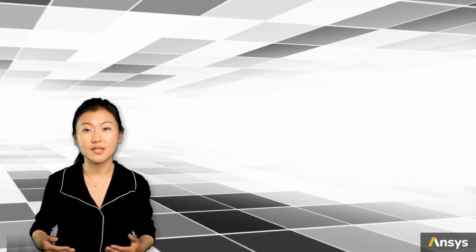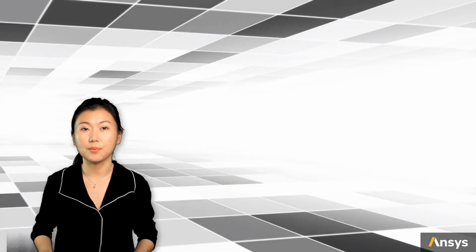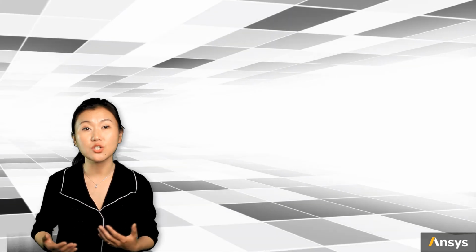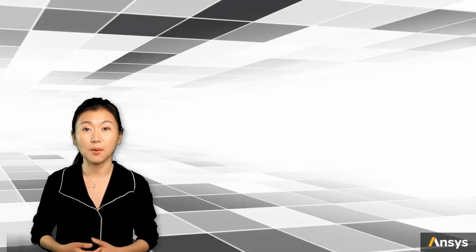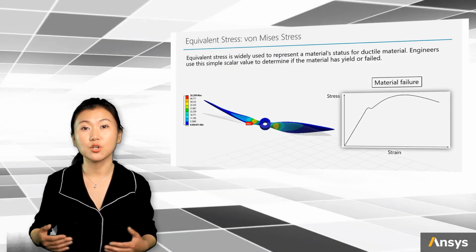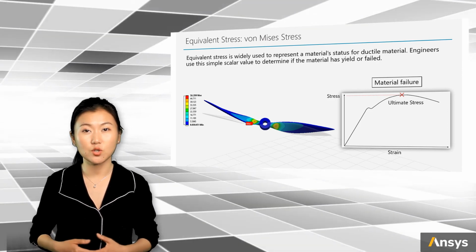In summary, we can see that only when the differences between the three principal stresses change, the von Mises stress will be affected. And that's why von Mises is a good equivalent stress to represent the distortion of a material instead of the absolute value of each stress component. Engineers use this simple scalar value to compare with material strength and determine if the material has yielded or failed.